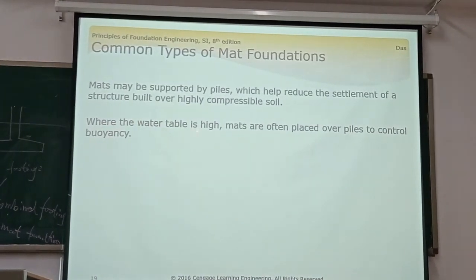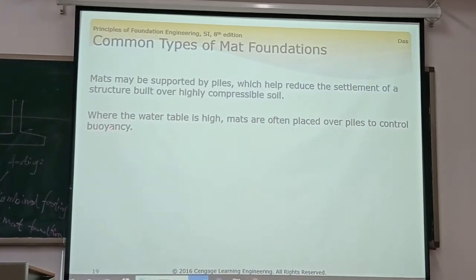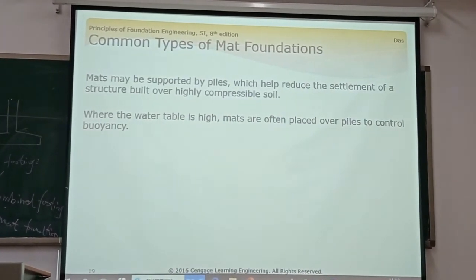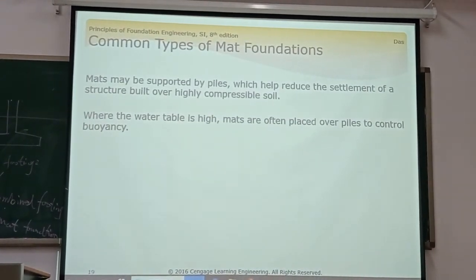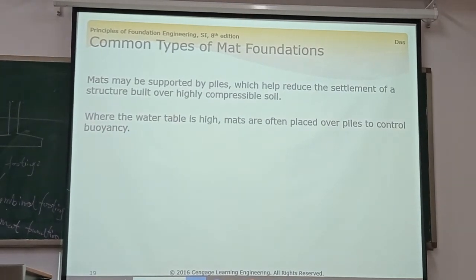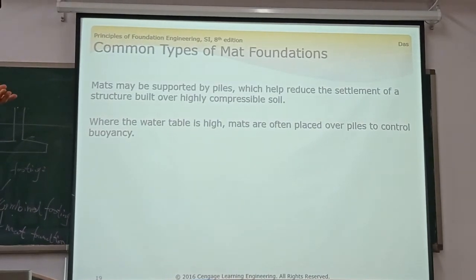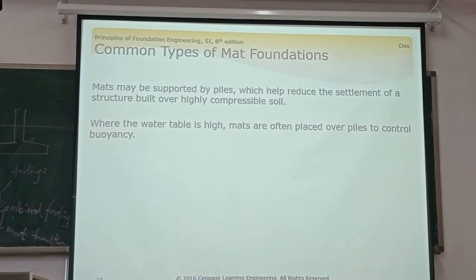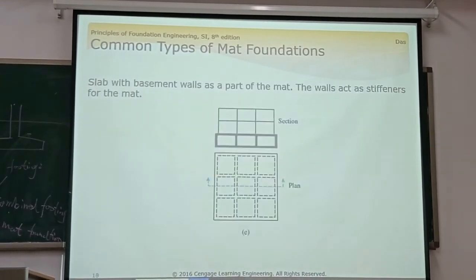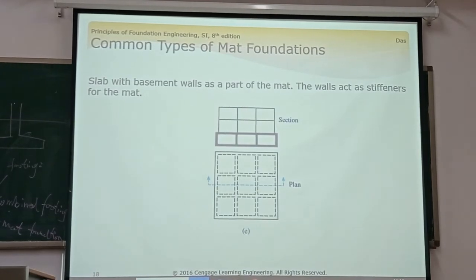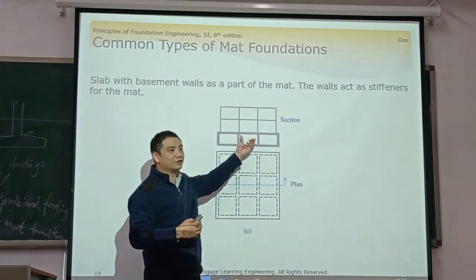Another case is where the water table is high. Mats are often placed over piles to control buoyancy. If with the buoyancy, the foundation may go up, it's not settlement. When the water table increases, the uplift increases. So the foundation is like a box. Because the box, the inside of the foundation is empty.